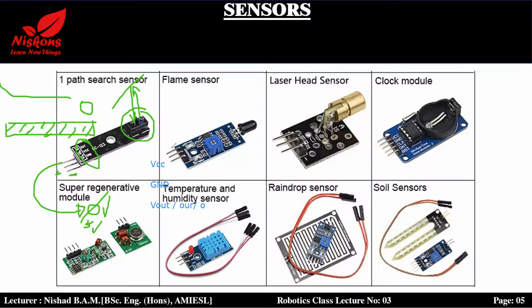Whatever sensor you take, it will have these three terminals, so don't get confused by them. What we have to do is first turn on the sensor. We power it up, V positive to VCC, battery to ground. Then we have the output voltage, and we can connect it to our relay or our Arduino.